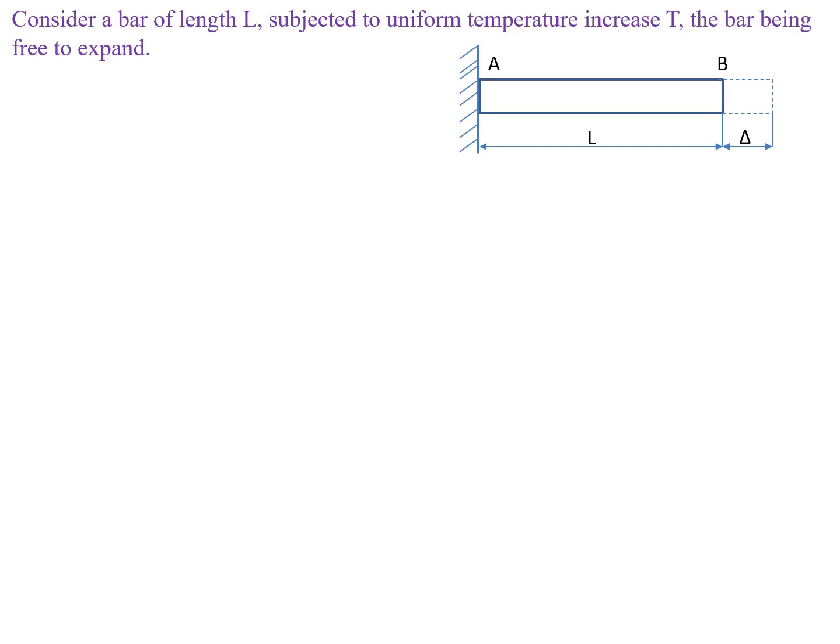When a member is free to expand, there are no thermal stresses generated in the member. The reason is, we know that stress is the resistance offered to the deformation. Here, there is no resistance to the deformation and the member is freely expanding. So there is no resistance to the deformation and also no stresses will be generated in the member.